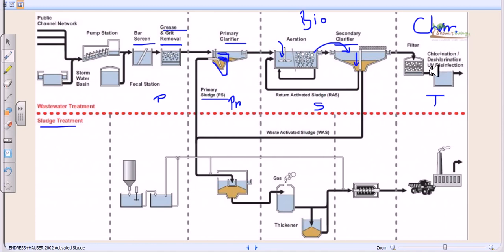That's why we need to remove the chlorine to some extent, or we need to bring the concentration of the chlorine down. We can do this by utilizing UV disinfection, or sometimes with the help of another chemical treatment by utilizing SO2. Sulfur dioxide is a very important key player in this case. So right after the treatment by sulfur dioxide or UV disinfection, our water is totally pure and it is ready to be discharged into the stream again.